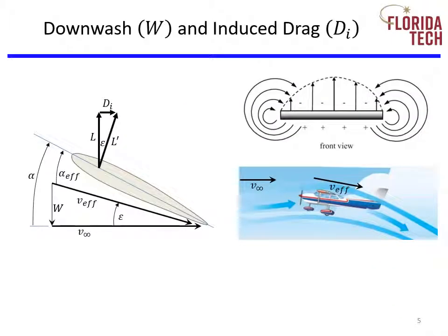These wingtip vortices are typically very large and will completely envelop the wing. The wing therefore sees a downwash from the wingtip vortices, stronger at the tips, a little weaker in the middle. In addition, these vortices will trail behind the aircraft and travel downwards in the atmosphere. These trailing vortices can last in the atmosphere for minutes, depending on atmospheric conditions and the strength of the vortices.